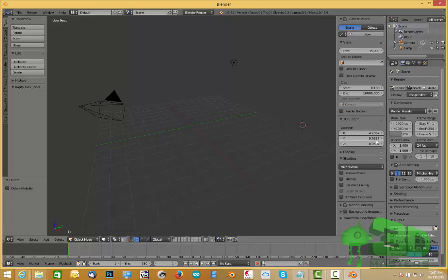Then over here on the side panel, you need to change your side panel. Now, I've already changed mine to 10,000, but yours is going to default to 1,000. So these models are not going to show up correctly. Here's some things you've got to remember about Blender. The coordinates are kind of messed up. When you're editing models, they're going to come out gigantic.